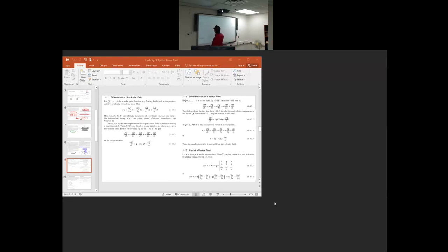If we look at this equation here, this is the change of the density, let's say, of the particular element if we go together with this element. And this one is if you stick to a particular point and find what kind of density is flowing through this point. So this is Eulerian description, this is Lagrangian description, but all of them are linked together, so we can describe one from another.